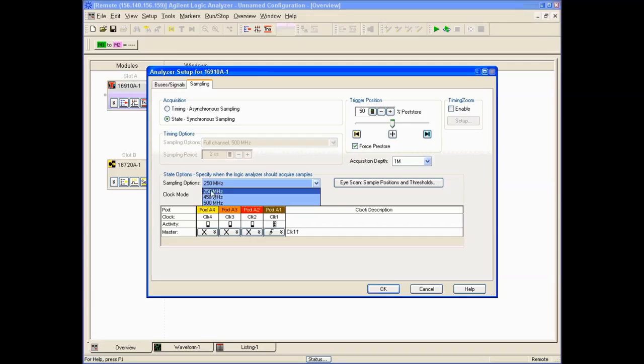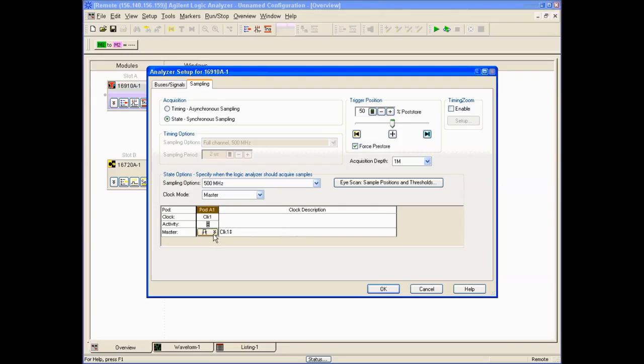And it doesn't just have to be a 250 megahertz clock. In the case of this logic analyzer, it's up to 250 megahertz. Certain options will get you to 450, or in certain cases, with 500 megahertz, it's going to force us into a, quote, dual sample mode. We sample on both edges of the clock, the rising edge and falling edge.